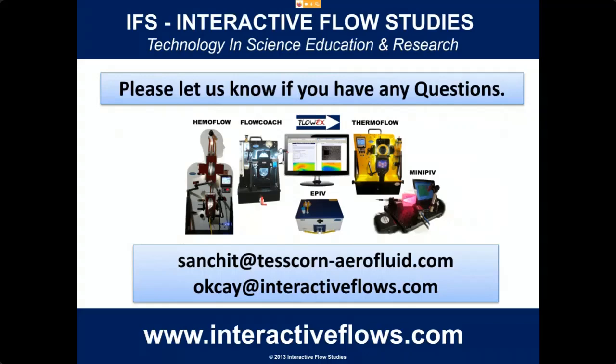First, what is the velocity range for the operation of mini PIV? We never tested the extremes, but I personally have done up to 5 meters per second. The area is important also because of the seed density and the laser power. So it depends which system you use: if you use 1 megapixel or 4 megapixel, or a 200 milliwatt laser, or LED, or the 1000 milliwatts.